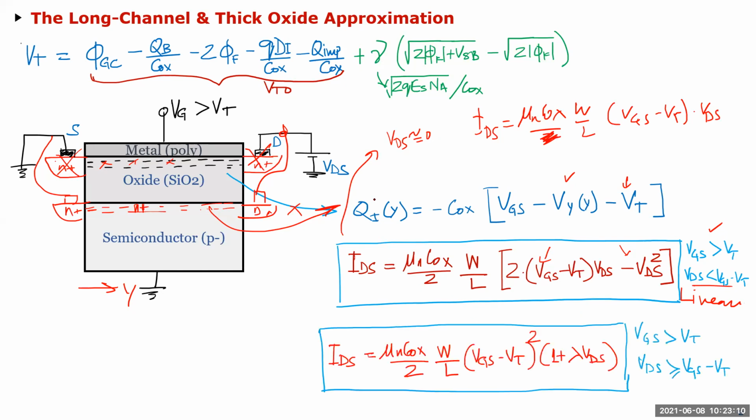And then we showed through the channel that once this channel area reaches VGS minus VDS equal to VGS minus VT, then essentially the channel density here becomes zero. So what we call the pinch-off region, and then the electrons just accelerate through.